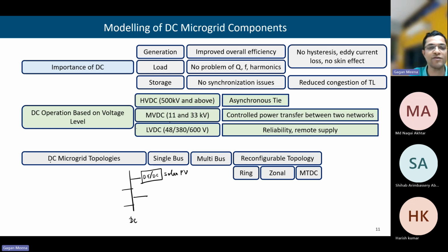And when we connect it to the AC system, there also we have two stages: one grid side inverter and one generator side inverter. The generator side converter will have that MPPT algorithm, and the grid side will have that inversion operation. Both can even be clubbed in one single stage also. The inverter will perform both the inversion operation as well as MPPT.